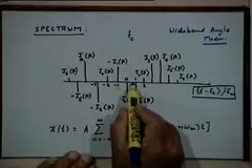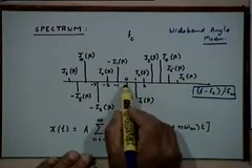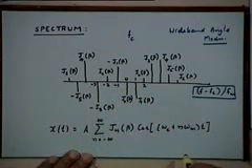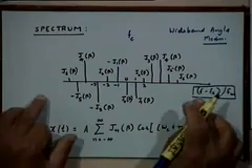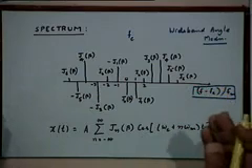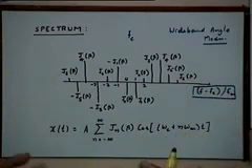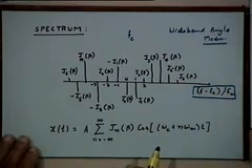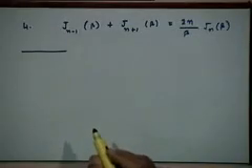Unlike the three line spectra that an AM signal has, the FM or PM signal will have a large number of lines corresponding to just the presence of a single frequency modulating signal at the input, right. So that's the important point. Any questions before I proceed further? No? Good, let's proceed. So these are some of the important properties of Bessel functions and this is what they look like.